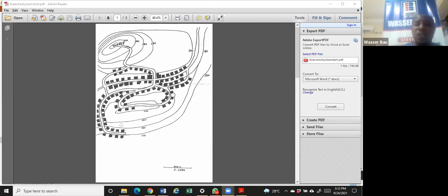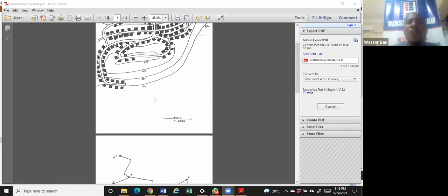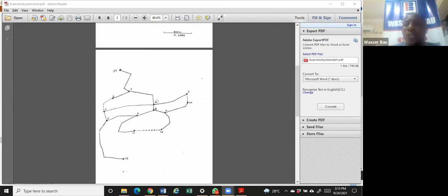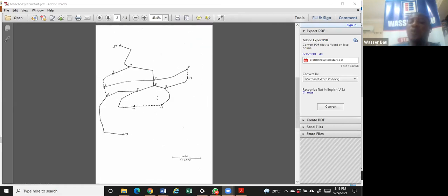So this is a case study of what we're going to look into. As you can see, those black dots represent buildings and the lines represent the elevations, or as we usually call them, the contour lines. Now, when you finish your network, this is what your network is going to be like. You're going to follow the path of the right of way, the path of the road, because you're not going to follow your pipeline through people's property.